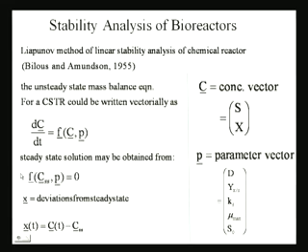Because what we want to do is give small perturbations into the system, and small perturbations are always available in the system, because in a real system you always have noise, as we discussed, and we want to see how the system behaves with respect to these small perturbations. Do the perturbations increase with time, do they decrease with time, or die away? If they decrease with time and die away, then the system is stable. If they stay with time and increase over time, then the system is unstable.